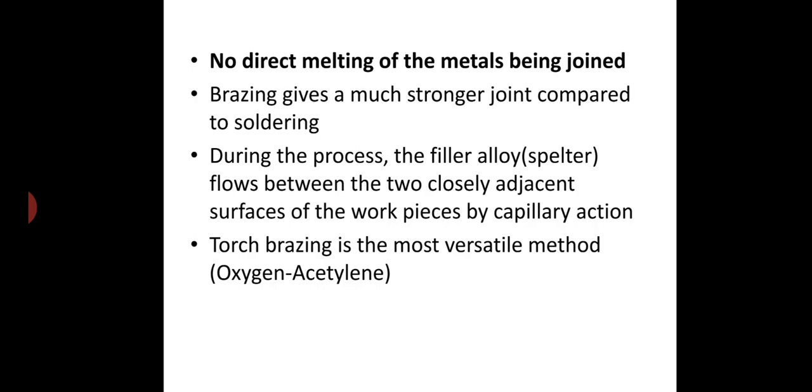Why we are utilizing brazing is that it will give you a better joint than solder. There is no direct melting of the metals being joined, similar to soldering. Similar to soldering operations, the filler material flows into the two closely adjacent surfaces of the workpieces by capillary action, and that will do the joining process.